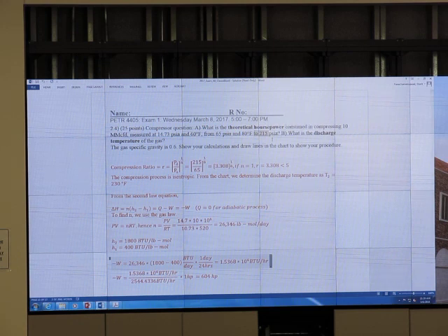If the discharge pressure is 10 times more than this, if you use just a single stage, the compression ratio will be a lot. Then you do 2 stages. If you do 2 stages, what is the compression ratio per stage? If it is between 3 and 4, you stop and you use that number. If it is more than 4, you add more stages. Just that. Good? Try single stage first. If the compression ratio is more than 4, try 2 stages, 3 stages, 4 stages, etc.